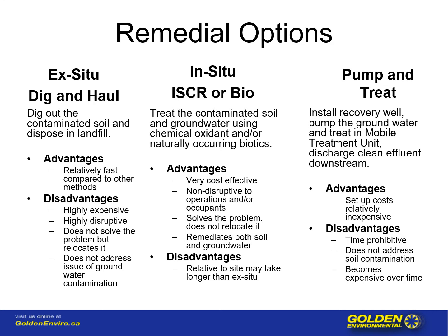The oxidant is chosen according to many different factors, such as lithology, hydrogeology, location, whether or not there is infrastructure, buildings, groundwater levels, types of contaminant, and one can use many different combinations of these oxidants in order to reach their remedial objectives.